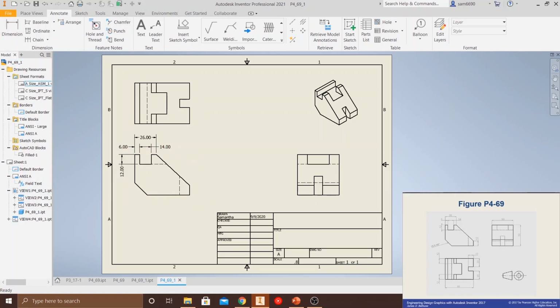Now, let's measure this height right here. We're going to get 12. Look at that. Click OK. So now, next thing we're going to want to do, we're going to want to come over and click the Chamfer button. Should be able to just click on it. There you go. So, how the chamfer works: you click chamfer, and you click the line that you chamfered, and a line right next to it. So this line will give you what your degree is off of mainly. So here we go.